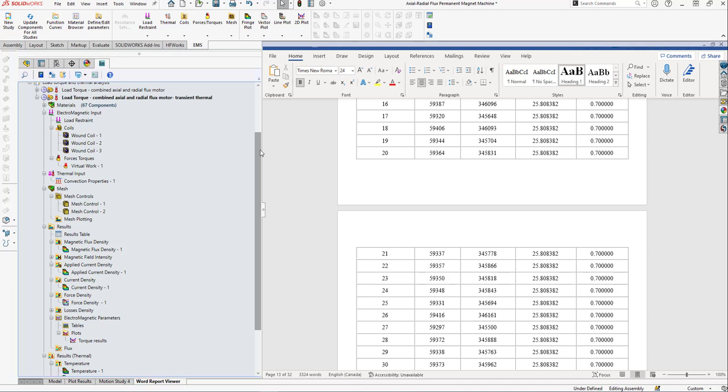Yet there is a drawback that must be overcome before making it a viable machine: the axial force acting on the axial rotors, because we know that a large force can deform or even break the rotors altogether. Another drawback is the cogging torque. The initial cogging torque for this type of machine is also higher.